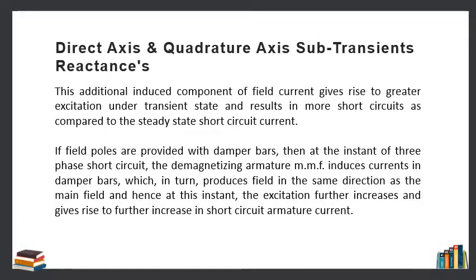The additional induced component of the field current gives rise to greater excitation in the transient state and results in more short circuit current as compared to the steady state short circuit current.